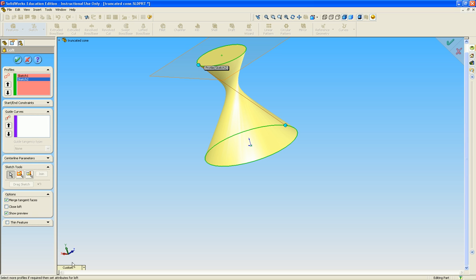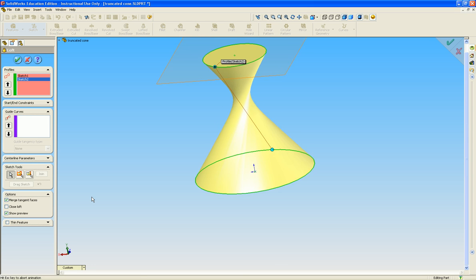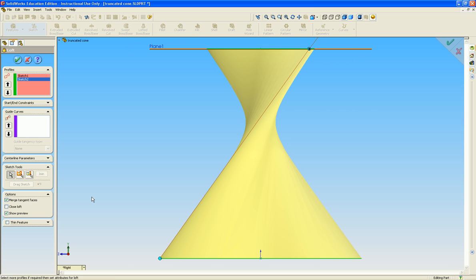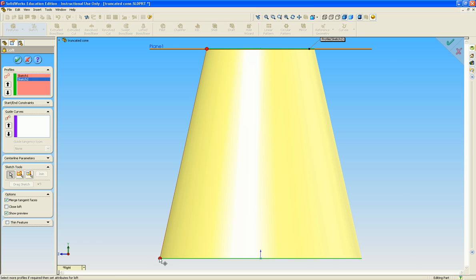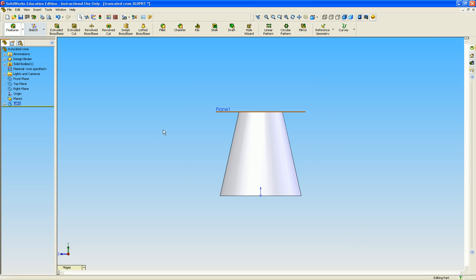To get the generator to be the maximum, what you can do is look at the right of it, and you can line up the generator so that it's in line at both sides there. Pull it out there to that side and do the exact same thing at the bottom, and you can do the vice versa for the minimum. Pull it over to the other side and you can see that you can't get it. You can get near enough to it, but you can't get it. So you can tick OK to that, and what you've drawn there is your truncated cone.